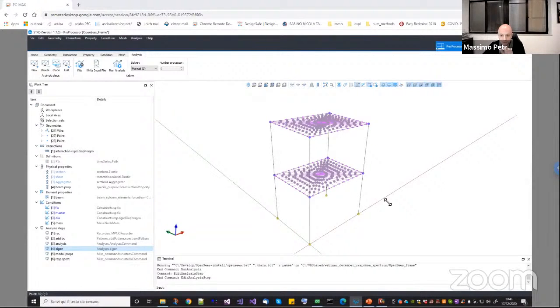The problem is that if you do this analysis at the beginning, there is no displacement in the model. So the initial stiffness of your compression-only element at a displacement equal to 0 will be equal to the full stiffness. So for an eigenvalue analysis done at the beginning, you will always have full stiffness. So in your case, you should consider only one of the 2 trusses.